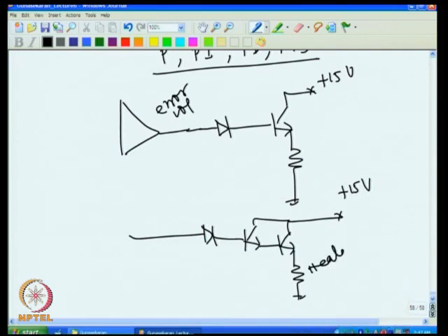Here this current is multiplied by the beta of 100. Suppose here it can be maximum 10 milliampere current, which means up to 1 ampere current can come, and this can take up to 20 ampere current, because HFE of this high power transistor is only 20, for example 3055. So we can have a heater drive like this, which can give high power, and this also can dissipate a high amount of heat, and a heat sink can be utilized for this purpose.